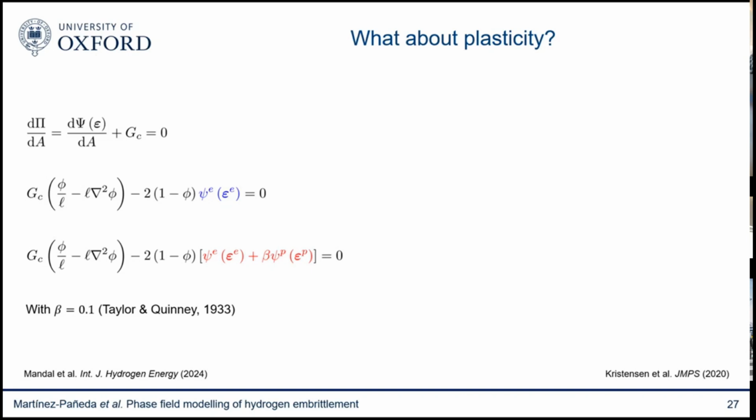And this was easy for him because then, for the fracture energy, he didn't have to do a fracture experiment. There was no fracture mechanics theory back then, but he could relate this to the surface energy. What happens if you want to look at plasticity? Well, of course, thermodynamics also holds in the presence of plasticity, and Orowan in the 40s already said Griffith's relationship holds for plasticity as well. It's just that this fracture energy is not the surface energy of glass, or twice the surface energy of glass, as Griffith said, but it's a much larger quantity. That for steels could be 1,000 kilojoules per square meter.